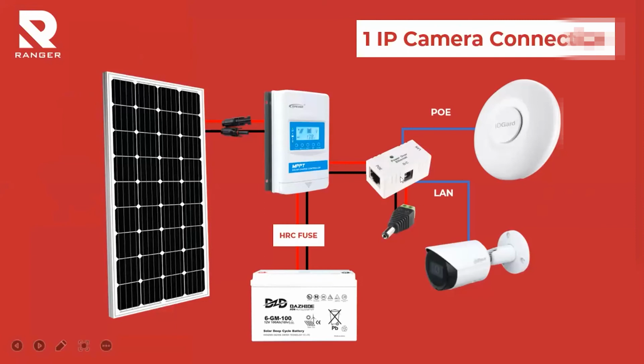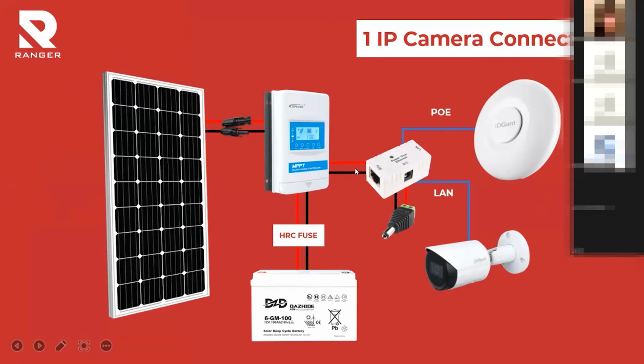The PoE injector will be powered up by an AC/DC jack male from the load output. 12 volt will power up the PoE injector, and the access point can be powered up. Then for the camera, an AC/DC jack from the MPPT connects to the camera power, and the LAN cable from the camera can be connected to this LAN port, so the signal can be transmitted to the main server.